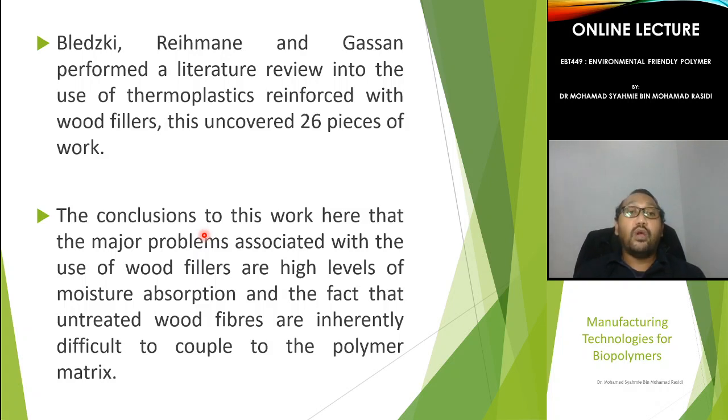As we know, wood filler is a natural resource. The hydroxyl content inside the wood filler is very high. This is the reason why it is really easy to absorb moisture. So how do we counter this problem? Modification has to be carried out to reduce the hydroxyl groups, so that the moisture absorption can be reduced.